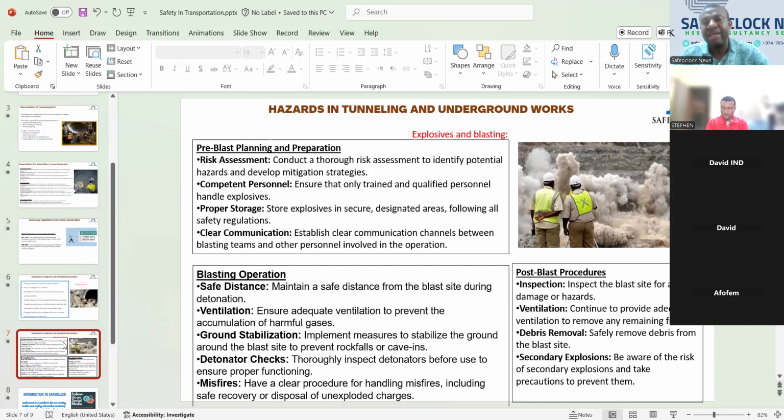Like during the tunnel construction in Qatar, we use explosives. But this explosive, of course, you know that they are regulated. You can't just bring explosive from anywhere or any time and start using. So you must go through the authorities and get the approval, and even during the blasting, the authorities will be around. They will create barriers, restricted exclusion zones, and only authorized people are allowed to do that blasting. That is to, first of all, create a better platform, a better space for the tunnel boring machine to be positioned. So you use this blasting to make the excavation easier.